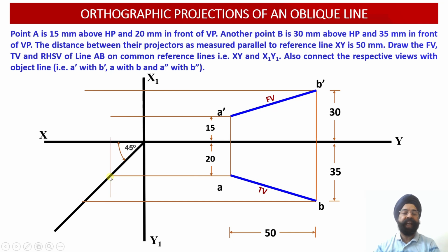two vertical projector lines we are now going to draw over here, which will be extending upwards, and they will be extended up to the coordinate location of the horizontal construction line which is emerging from A dash. Another construction line we are going to draw from the coordinate location of the point B, and it will be extended up to the horizontal construction line which is emerging from the point B dash in the front view. So please check, this point location will be B double dash, this point of intersection will be point A double